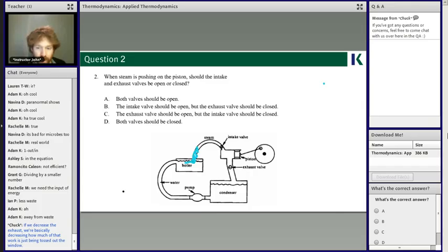This boiler is starting to boil. All the steam starts to come in. The steam enters through this intake valve, and then it basically hits this piston, and then makes this little turbine thing spin. And that's basically the work that it's doing, pushing against a piston or spinning a piston. I guess pushing a piston would make more sense, but basically it's making it do some work. And then we've got this exhaust valve, so the steam goes, we condense it, and then we can pump it back to the boiler and recycle the whole process.